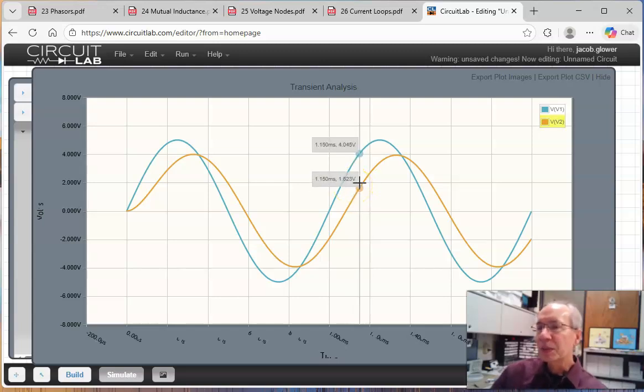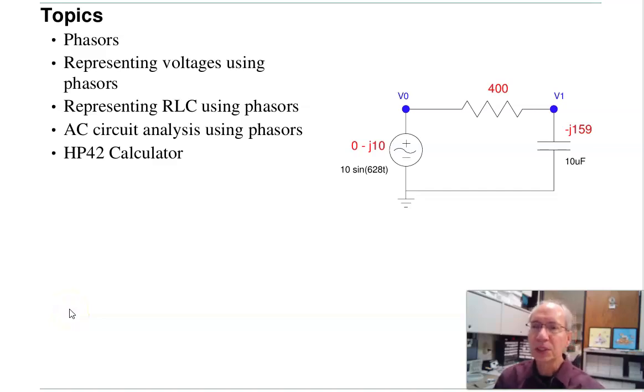So when you're dealing with sine waves, it's much simpler. All I need to describe the output are two numbers, amplitude and delay, or sine and cosine. So describing circuits with sinusoidal inputs is much simpler than other inputs because sine waves are eigenfunctions. To describe a sine wave, I just need two numbers, the amplitude and delay, or sine and cosine. Those are complex numbers, that's phasors. And it's not really that limiting. It's only limited to sine waves, but with a thing called Fourier transforms, a future topic, I can represent any periodic signal with sine waves.